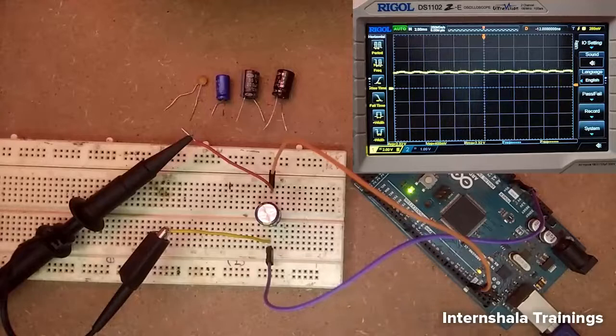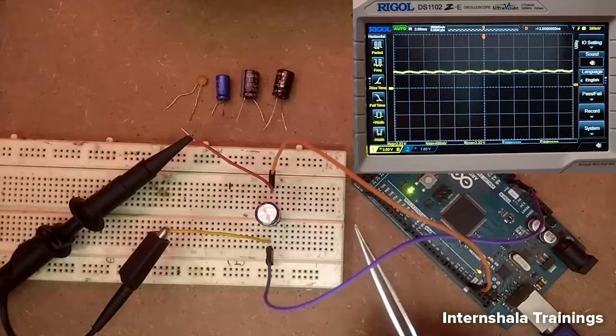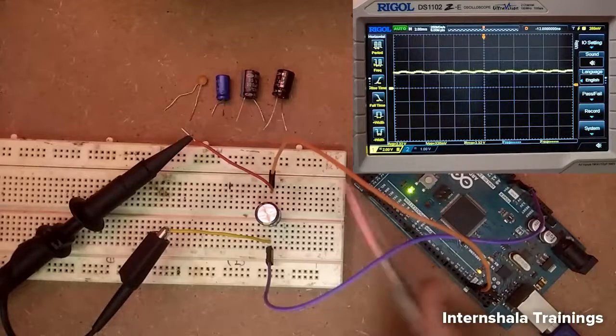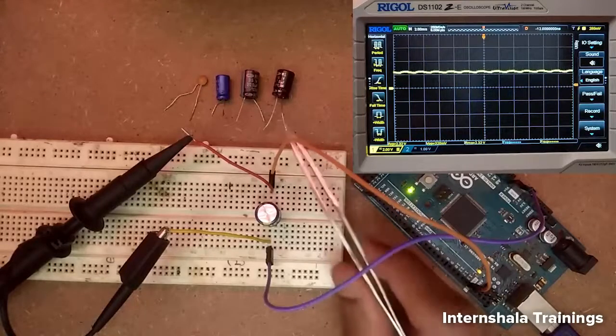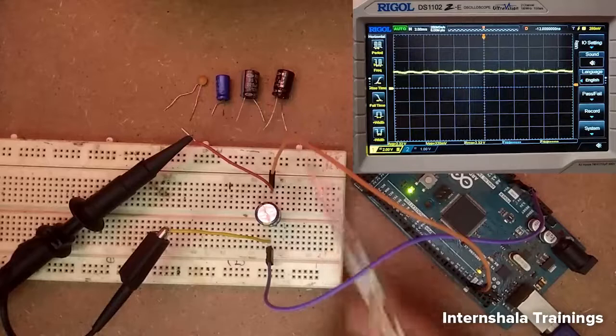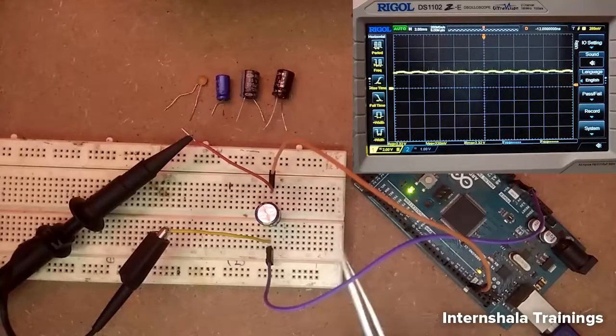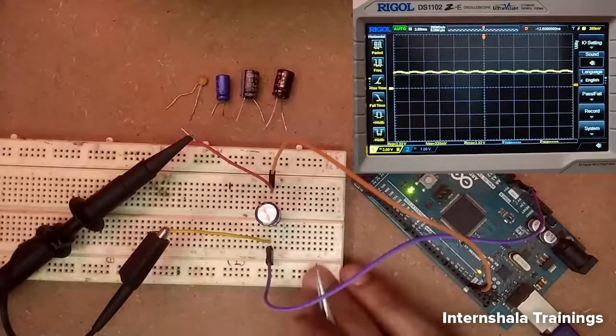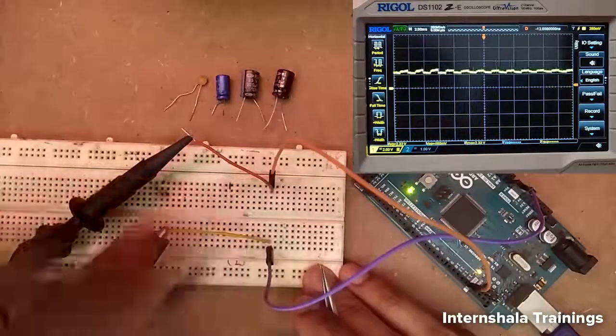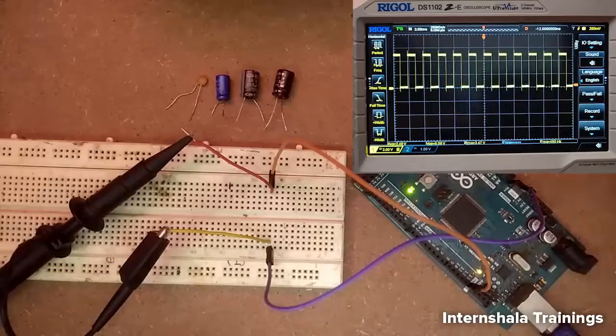Okay, so I hope that this point is now clear, how exactly a capacitor filters out the frequency or the noise. You can also consider this as a signal, or you can also consider this as unwanted noise. Here my purpose was to show you how exactly a capacitor filters out the frequency or the noise from the line. Now I will remove this 1000 microfarad capacitor, and you can see on the DSO again we are getting the signal of 500 hertz frequency.